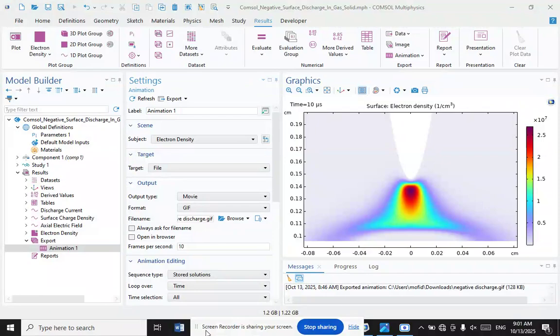glass surface. In several regions of the world where PV panels are frequently covered by sand wind, in the North African and Middle Eastern countries, solar panels should be cleaned frequently, which requires hard and time-consuming work, especially for the large solar panel arrays. There are currently three cleaning methods that are used for PV panels: mechanical, coating, and electrostatic